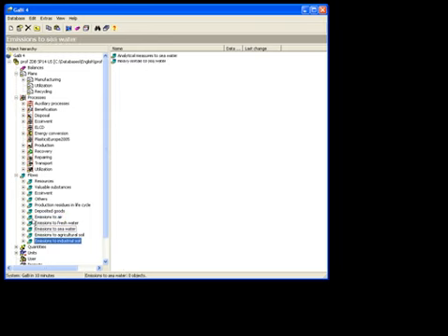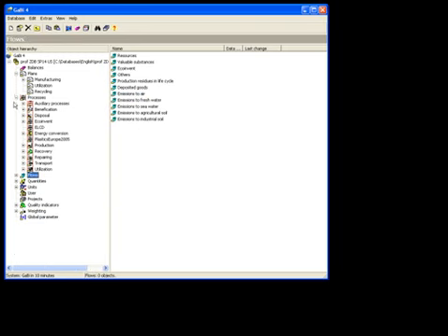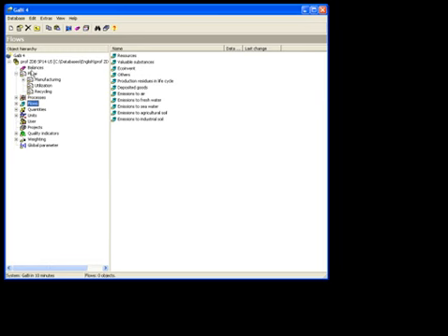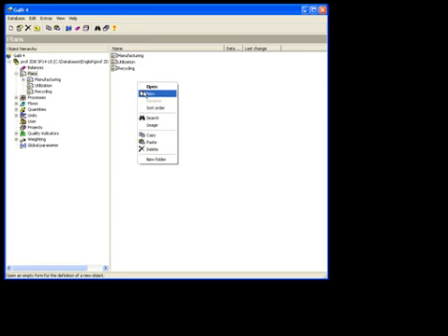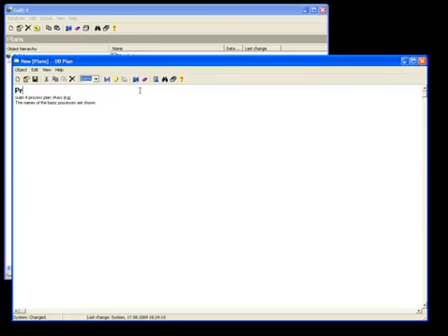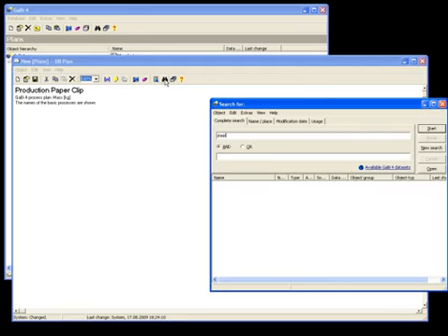On plans, all kinds of processes can be added and connected to reflect the process identified in real life. The plan then accurately represents the specific process that you are analyzing. By right mouse clicking and selecting New, a new plan can be created and its name entered. With the search function, database contents can be searched to locate existing processes. These processes can then be added to the plan simply by dragging and dropping.